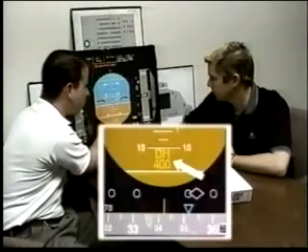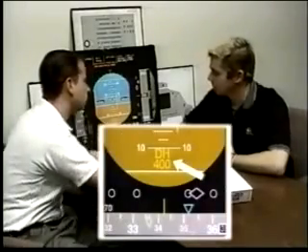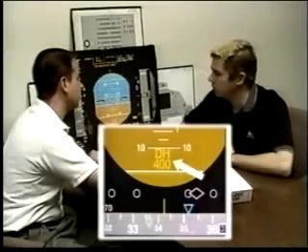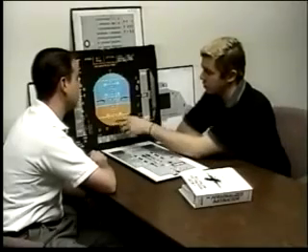Describe to me when you would get your RA, or radio altitude. The radio altimeter comes into play below 2,500 feet AGL. It'll be green all the way down to 100 feet above whatever RA or decision height we have set in the MCDU. It defaults to 400 feet if you don't enter one, and if you enter no for whatever reason, it would turn amber at 100 feet. DH will appear anytime you're at or below your decision height set in the MCDU.